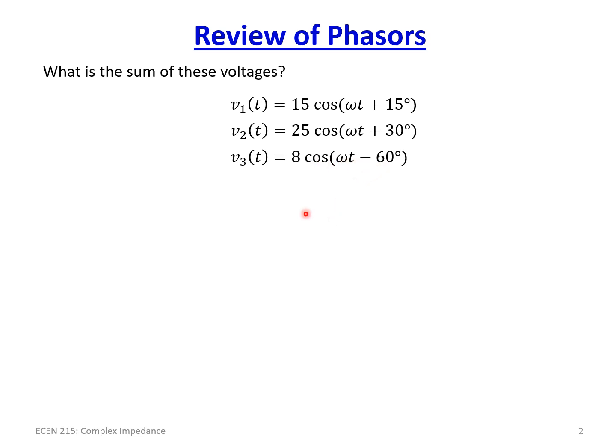And as we discussed the other day, the reason to represent this in phasor notation is to simplify the concept so we don't have to deal with all of these cosine terms when doing general mathematics on these signals. Since we're going to assume all of them have the same frequency and we are discussing AC signals that are periodic by nature, we can represent this in different notation named phasors.